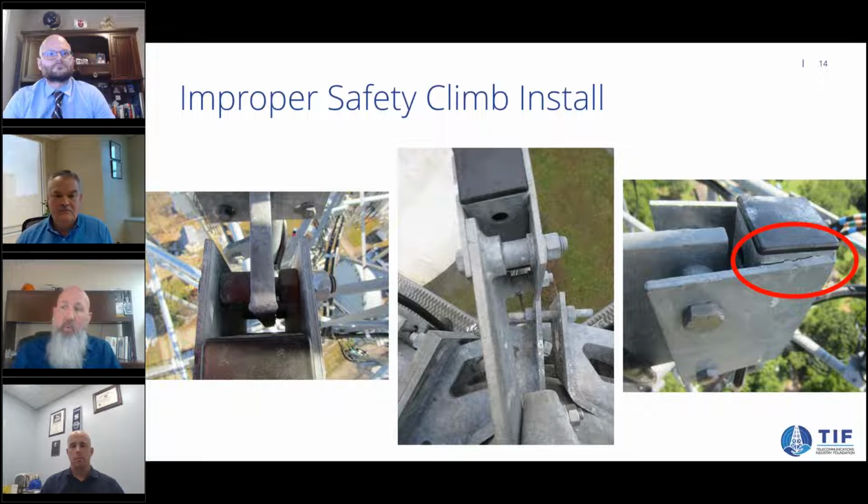In the far left photo, we've got a safety climb that's improperly installed because we've got spacers on one side and we have a nut on the other side, which is actually causing a gap between the head assembly and the mounting plate. This is not going to perform as it was designed.